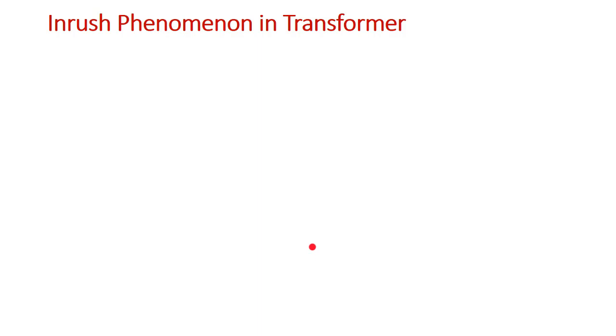So now this is all about the transformer protection scheme. We have not completed it, but this is about the differential protection scheme, in order to protect against internal faults which happen at the terminals of the transformer, right. It is not inside the transformer, because inside the transformer such faults like line to line, line to ground, and triple line faults do not happen. They happen at the terminals of the transformer.